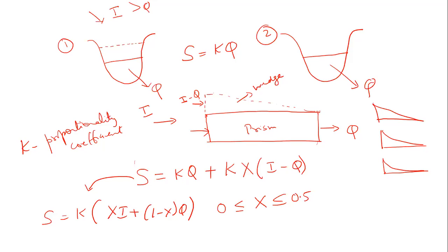So if I have uniform flow in the entire channel reach, I'll have Q here and Q here, right? But suppose I have set up a flow where I have some flow rate at the upstream end, I, which is greater than Q, and the flow rate at the downstream end is still Q because the effect of the flood has not yet reached there, right? The flood moves. It takes time for the flood to move from point A to point B. So if you assume that this reach is sufficiently long, then if you take a snapshot of time, at this cross section I have a flow rate of I, and at this cross section downstream, I have a flow rate Q, which is less than I.